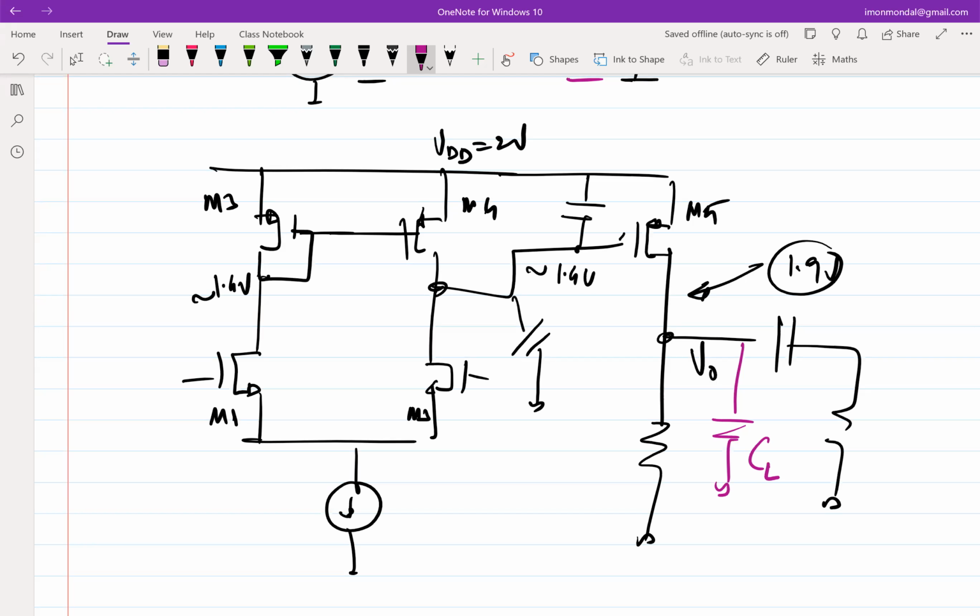Miller, right? Only one way we know as of now, other than putting a very large capacitance at a node, right? That is obviously one way to do it. You can say that I'll put some infinite capacitance in one node, everything is stable, right? But that will also be infinitely slow. You don't have too much loop gain if you have put a very large capacitance. So the fix is put a Miller capacitor, and if you put a Miller capacitor, the poles will split.